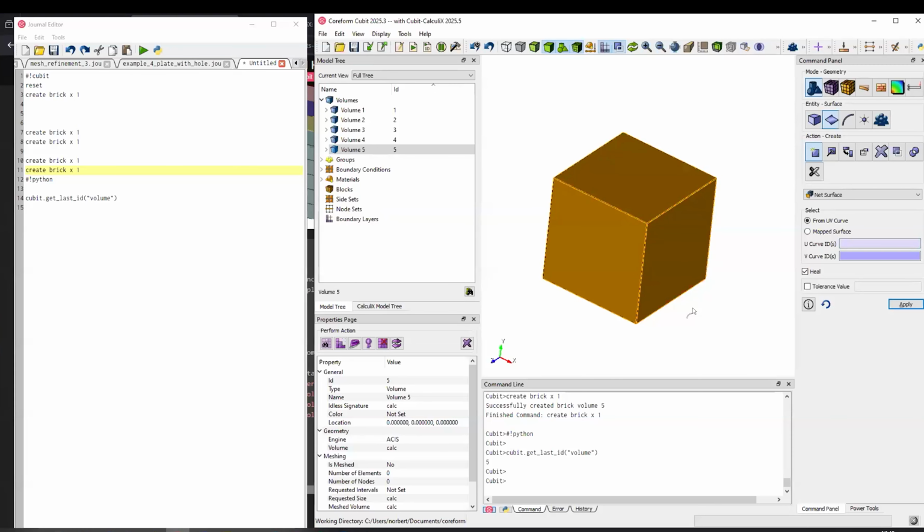It's extremely general, but it is possible based on the data. Yeah, I think you're the person who's going to know best, Kirill, how your data is structured. If you have some structure to your data, such as lines of equal X values, you can say I know my data is organized, or maybe I can do a sort, and I can create spline curves of equal X values, and then I can connect adjacent curves in the Y direction to start to create those.